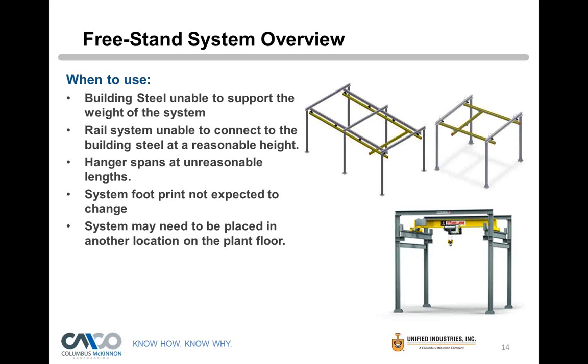That's a good point because, like you said, you want to make it versatile because things always seem to be changing. But I have a question for you on this. What is your general specification and how you anchor freestanding structures? Sure. What we do is, for most structures, we recommend a 6-foot embedment with 3,000 psi reinforced concrete. Typically, we use wedge anchors or the adhesive anchors.